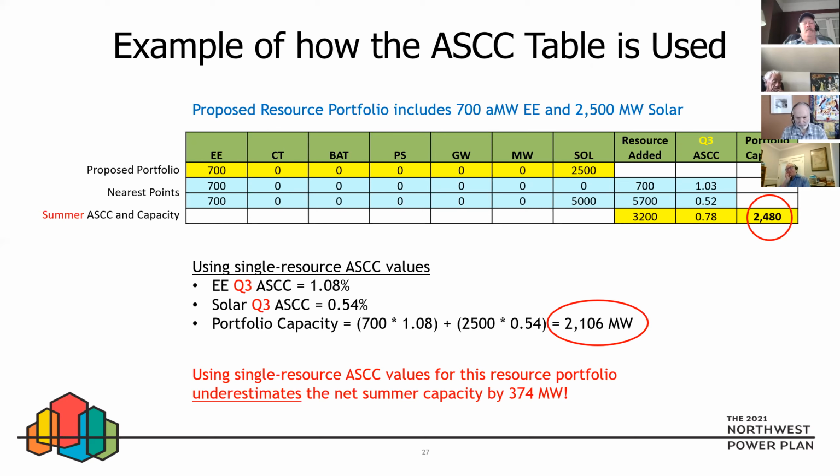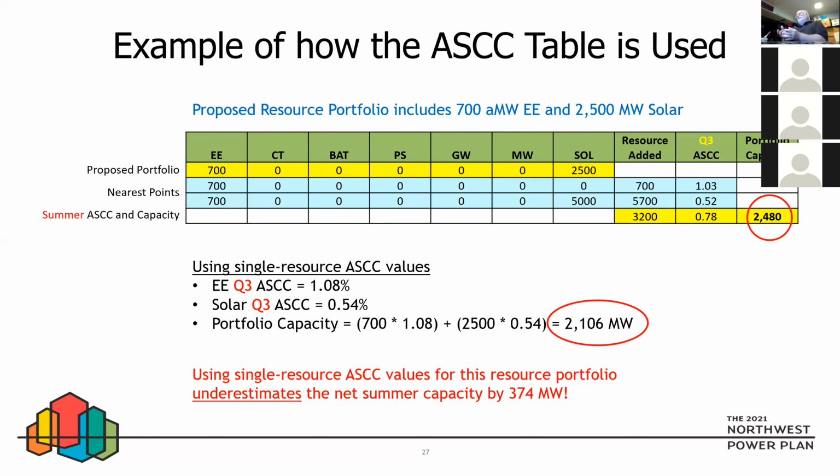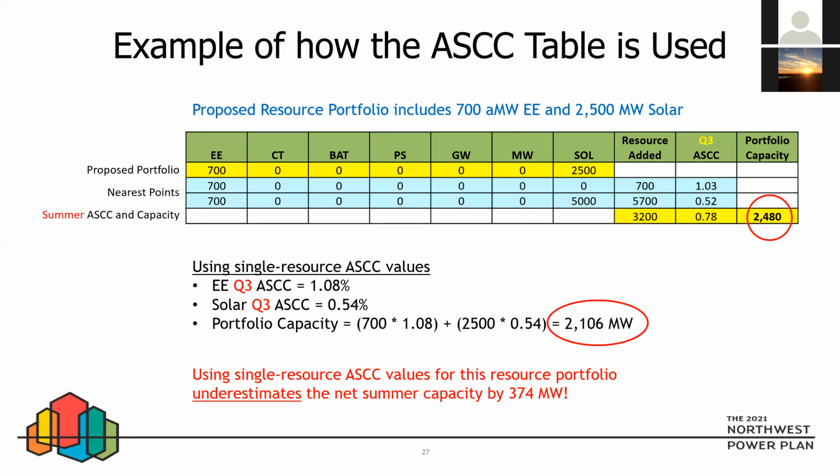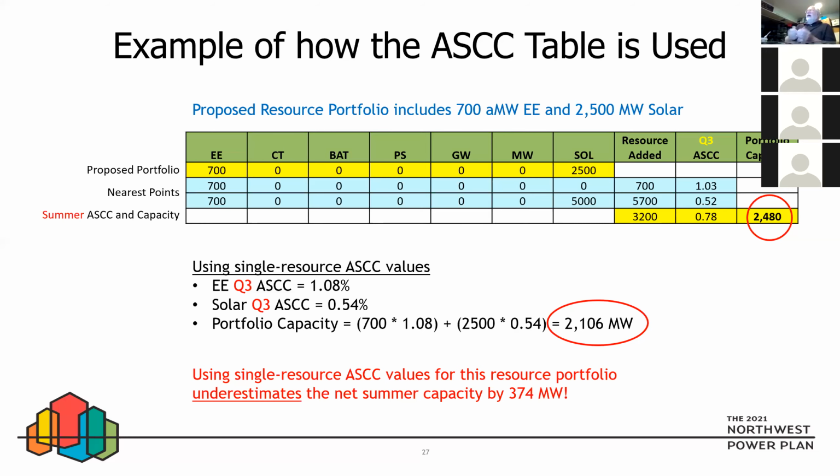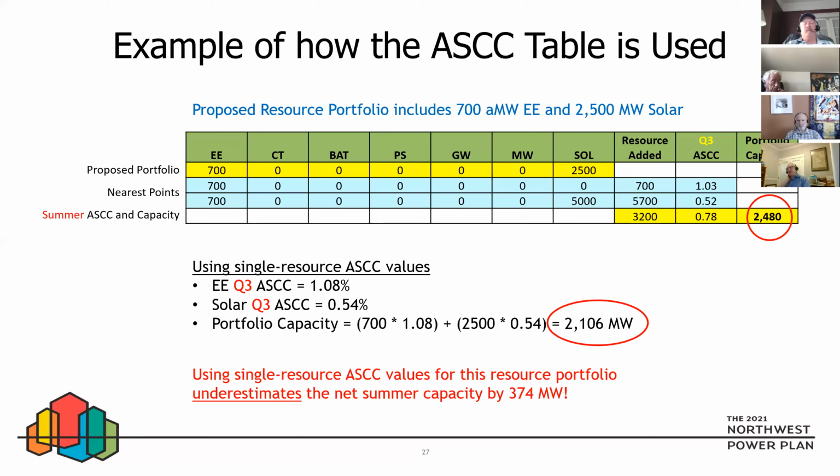John, it seems to me like you're going to have behind the meter resources that are going to avoid transmission and distribution losses. You're going to have things like batteries at substations that will avoid transmission but not distribution losses. And when you're just showing 700 megawatts, I can't tell whether that's 700 megawatts at the meter, at the substation, or at the generation level. There's a big difference, because as I indicated in my paper on marginal line losses, it could be 25% at critical hours.